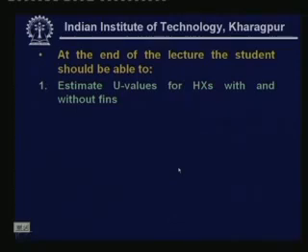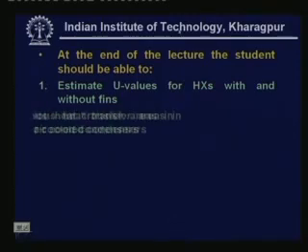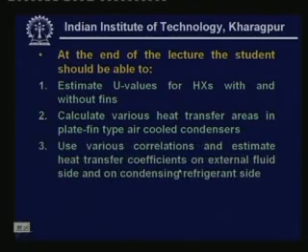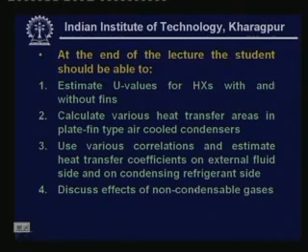coefficient values for heat exchangers with and without fins, calculate various heat transfer areas in plate fin type air cooled condensers, use various correlations and estimate heat transfer coefficients on external fluid side and on condensing refrigerant side, and discuss effects of non-condensable gases.